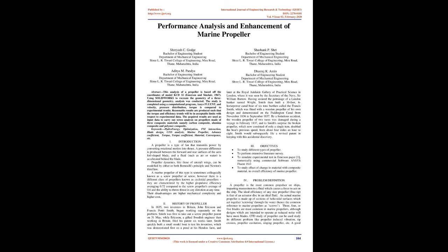Using SOLIDWORKS to recreate the three-dimensional geometry, analysis was conducted. The study is completed using a computational program, Ansys FLUENT, and velocity, pressure distribution, and torque are compared to experimental results. Reasonable results are produced such that the torque and efficiency trends will be within acceptable limits with respect to experimental data. The acquired results are used as input data to carry out stress analysis on propellers made of three composite materials, namely carbon composite, alumina composite and polymer composite.